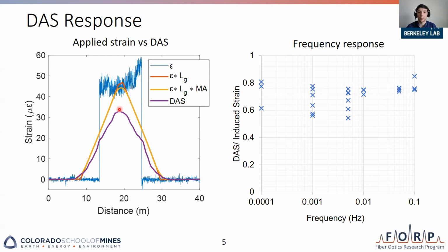And that's also what we probably see in Veronica's work, where we have some mismatch between DSS and DAS. So there could be some different explanations for that. It could be calibration of the system. And another thing, if we pre-strain our fiber first, it could slightly deform our waveguide, and it also could cause some difference in our strain measurements.